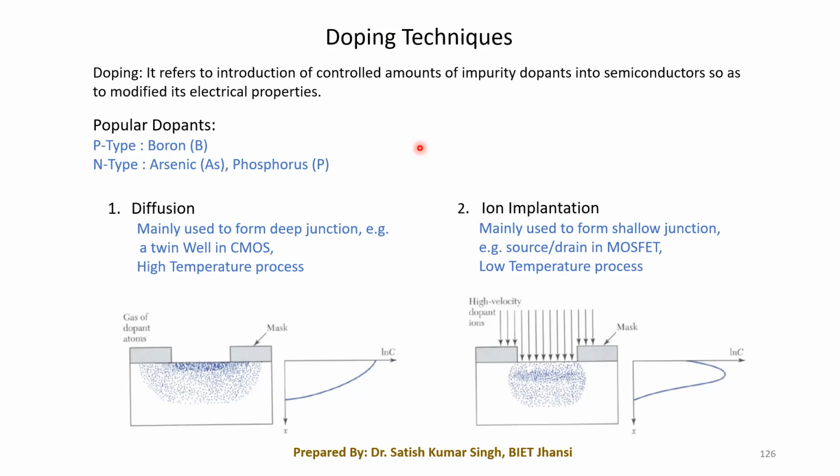These are the popular n-type dopants, and they give an extra electron in the conduction band so that conductivity can be enhanced. Similarly, we can add p-type dopants like boron, a very popular dopant that increases the number of holes in the elemental semiconductor. This way we can perform doping to enhance the conductivity of the semiconductor.